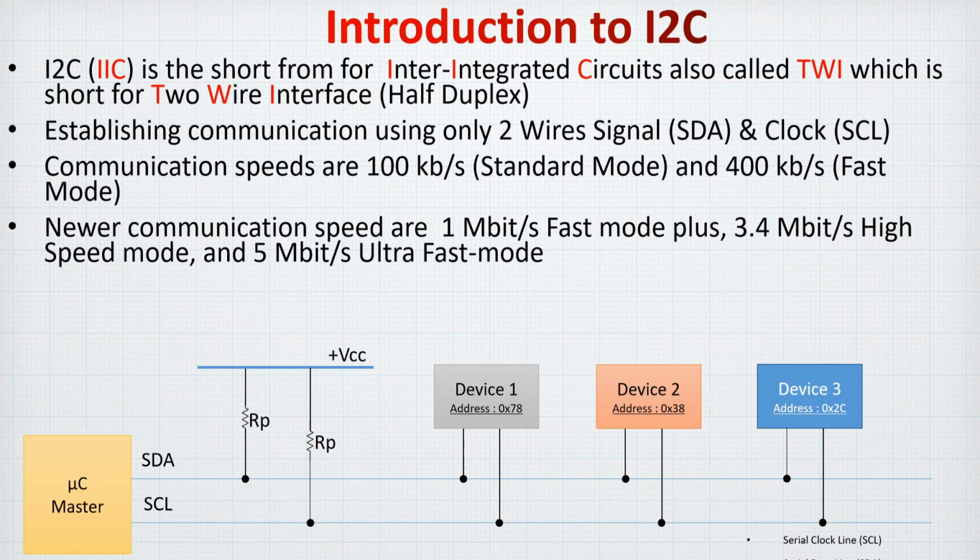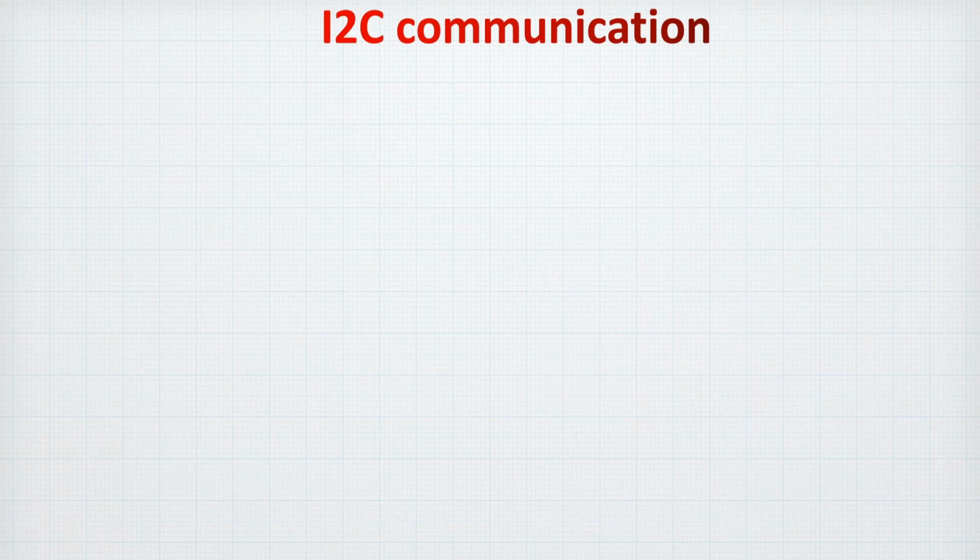After that, you connect devices to the wires for the SDA and SCL. As you can see, each one of the devices will have a specific address, and the communication will go by signaling this. Based on that, normally you can add up to 127 devices. But in reality, it's not possible to do more than 30, because there are more noises and some parasitic signals, but 30 is already something really good. Okay, so now we have introduced a bit the I2C. Let's take a look more at how the communication works.